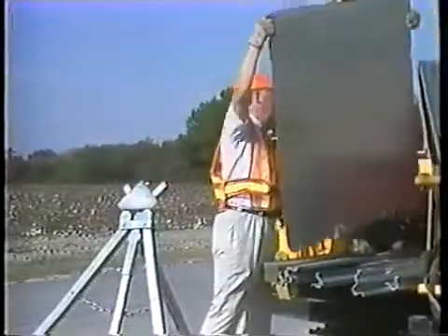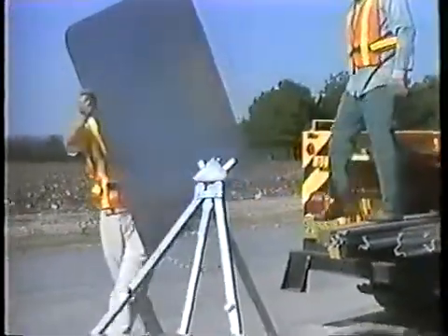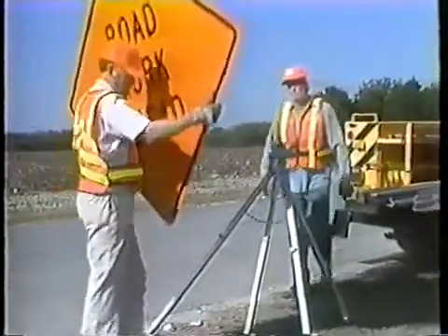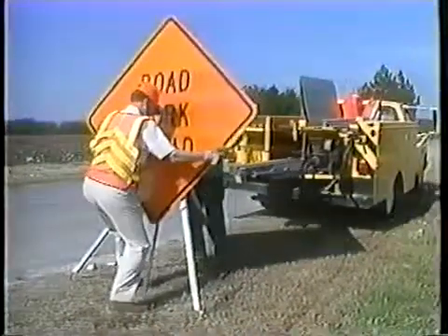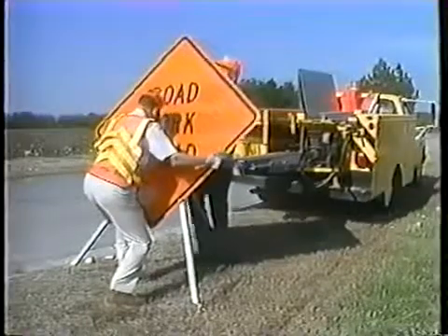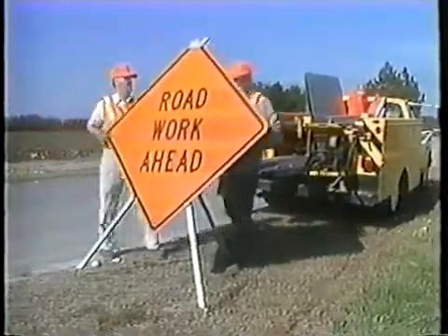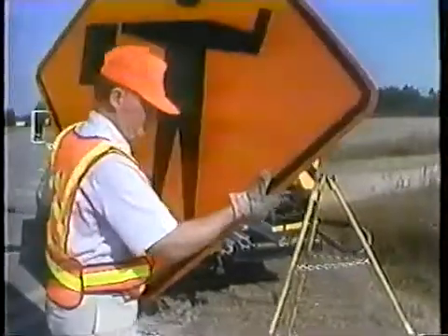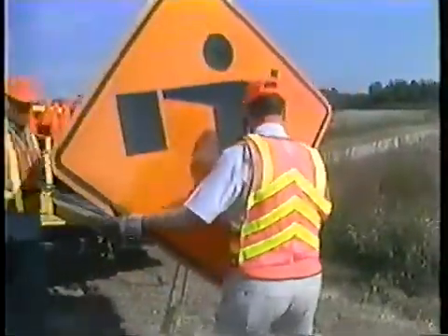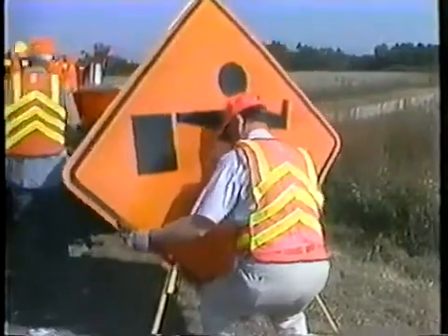Remember, in all situations, the primary purpose of traffic control is to warn and guide the driver while he or she is approaching or passing through your work zone. You are probably most vulnerable during the installation of the traffic control devices. To minimize this hazard, install the devices before work begins, starting with the first device the driver will see when approaching the area. Then continue installing devices, advancing toward the work area.